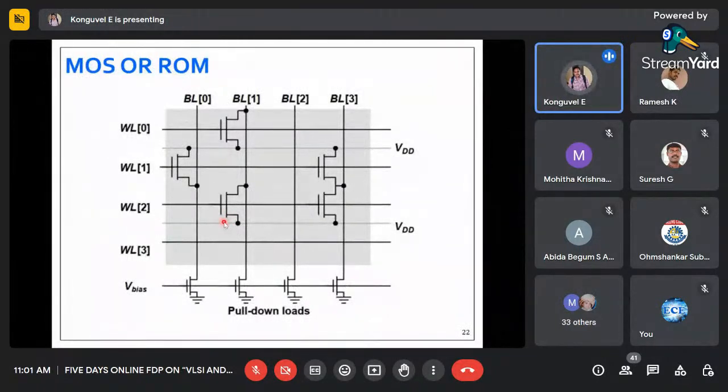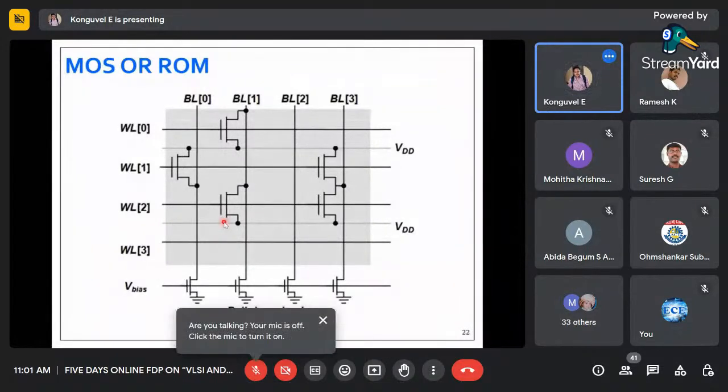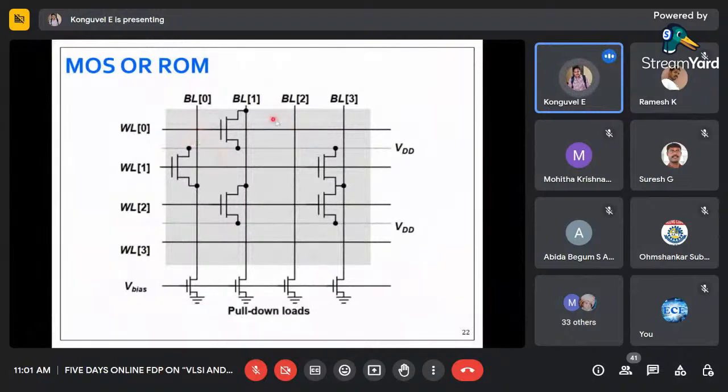So now coming to the NOR ROM, mask ROM. These are all simple concepts, and based on the topology we get the name. I'll tell how. First, in all the crisscross points we will have a transistor, and we are programming the transistor to be non-operational. That is what we are doing here. So we have not programmed only these 5 transistors here. See how.